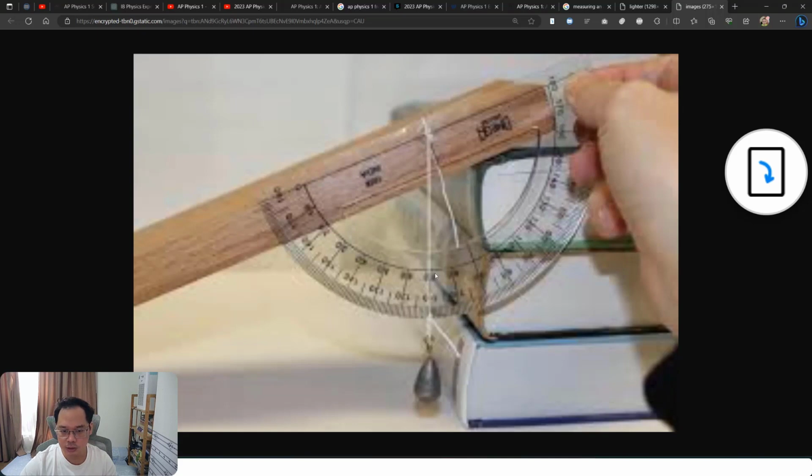Use a light, small string and attach it to the center of the protractor at this point, with a weight hanging at the bottom of the string. When you put the protractor along the incline like this, the angle that the vertical string makes with the 90-degree direction, the direction perpendicular to the incline, is the incline angle of the surface.